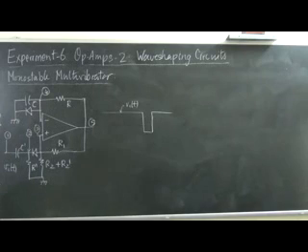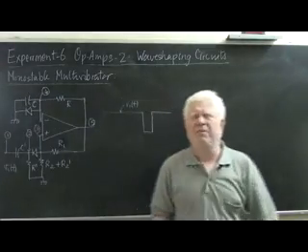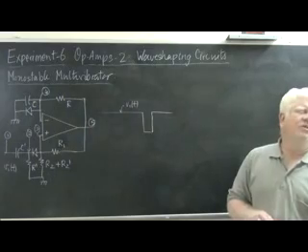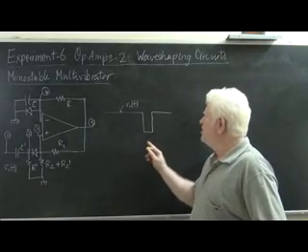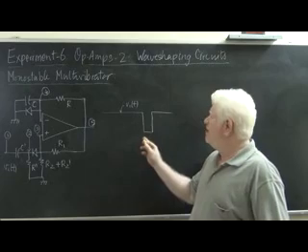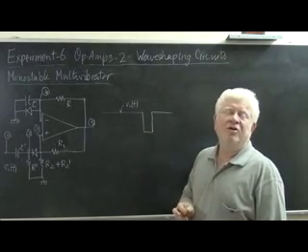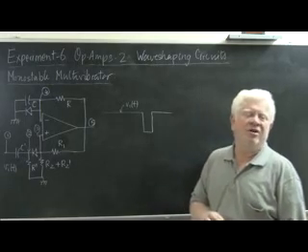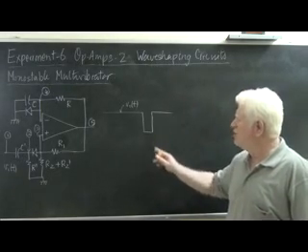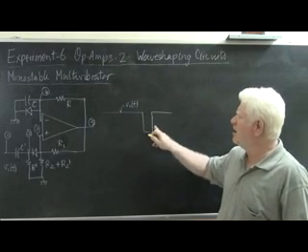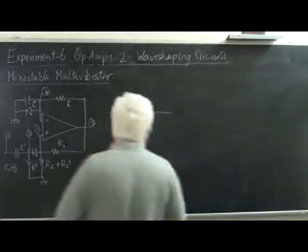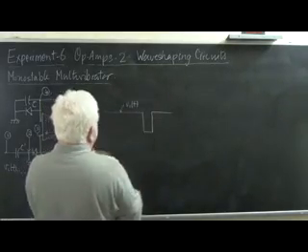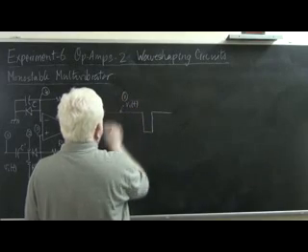Okay, now what has happened is there was a square pulse and this square pulse passes through a differentiator. So the differentiator will do what it does, that is, it will try to be constant, try to be 0 wherever the input is constant and try to give a spike wherever the input undergoes a transition. So this input undergoes 2 transitions, as you can see, one over here and the other over here. There is a downward going transition, there is an upward going transition. So the result, this is waveform number 1.